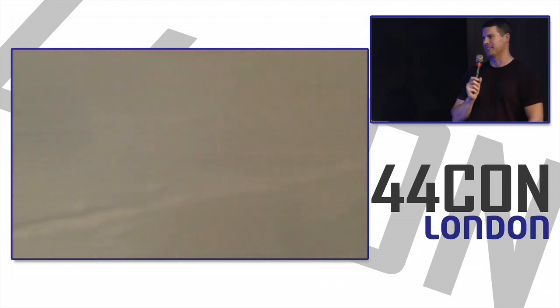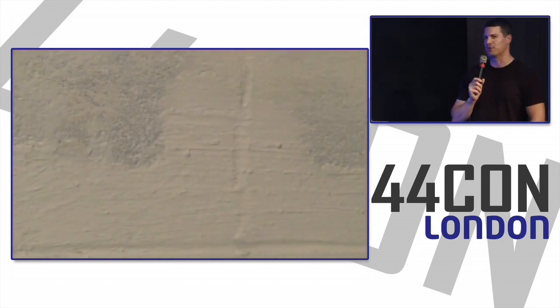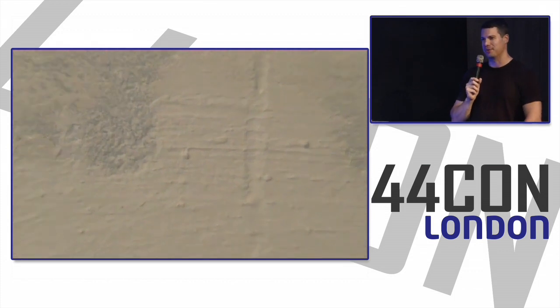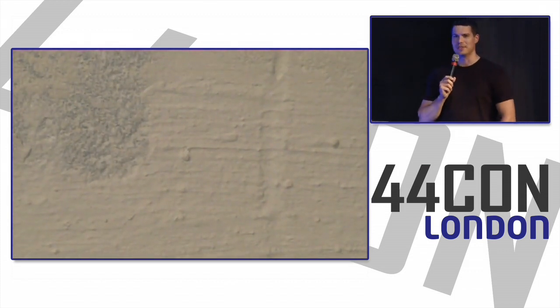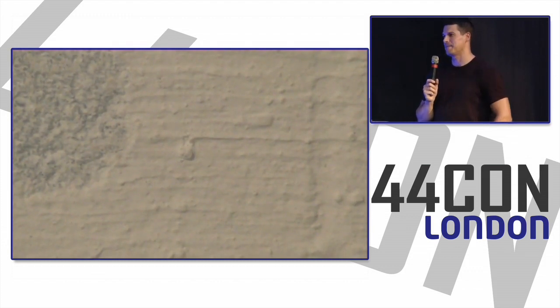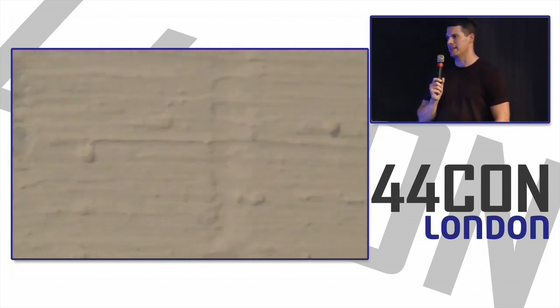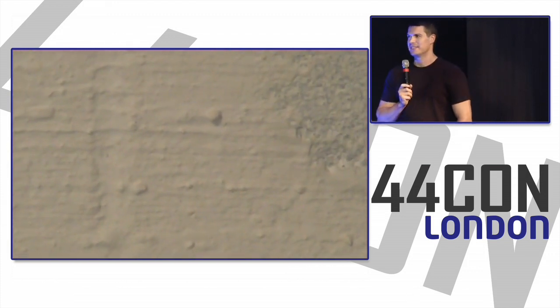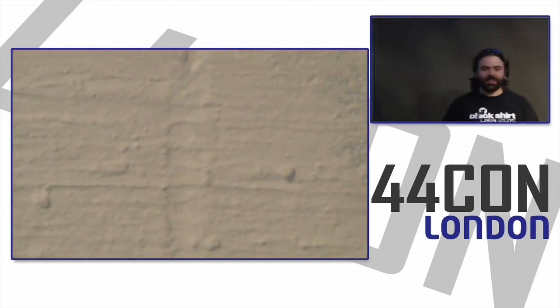So in order to read things back out, your JTAG adapter is running at 1 or 2 megahertz. So your total actual bandwidth of reading stuff out is terrible. It's 1 megahertz divided by 500 pins minus the overhead, times 8, minus the pins that we're actually using, times however many clock cycles you need per byte. It's bad. Long time. We didn't even want to do the math. It was so hard.